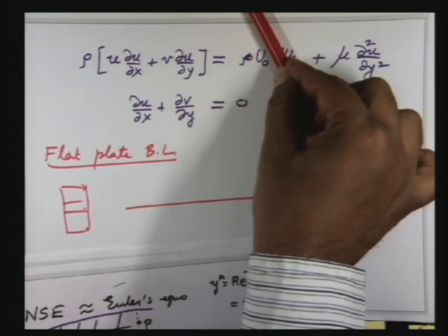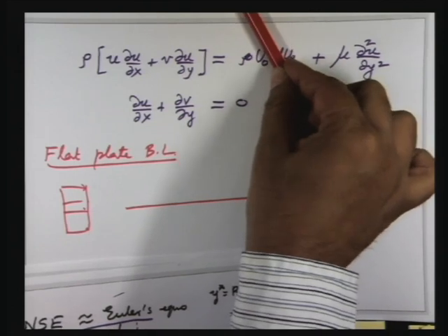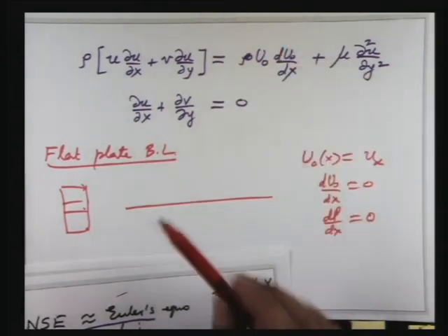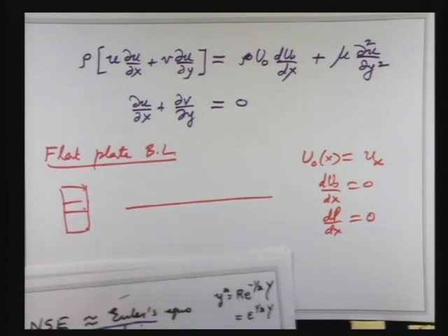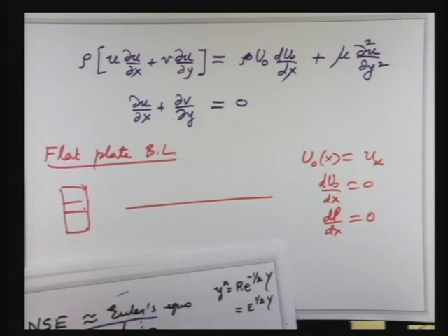But there you are going to have boundary layer flows where this could be plus or minus. And maybe in the main workshop we can talk about what is called favorable pressure gradient and adverse pressure gradient, and we will show that when you have an adverse pressure gradient, there is a possibility of having a reverse flow near the wall, which is called boundary layer separation.